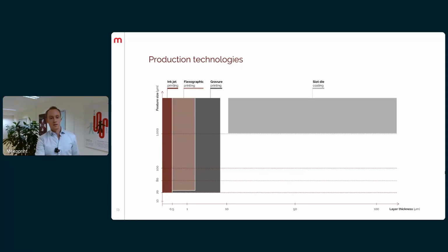At MakerPrint, we use roll-to-roll screen printing, with the option for prototypes in a cheaper sheet-based setup. And we find this to be the ideal solution if you have fine details, but also need a specific layer thickness for your sensor to work, and also the ability to get started and make changes at a relatively low cost.